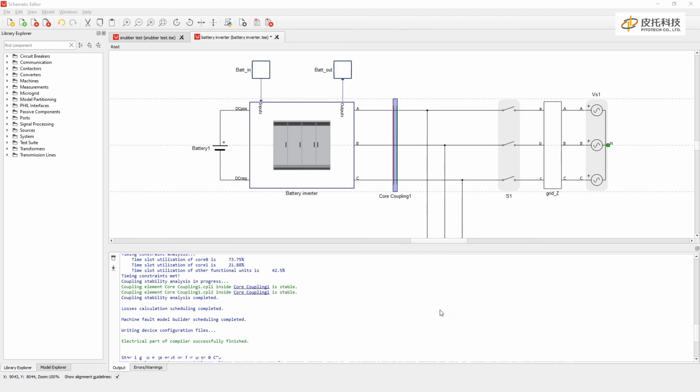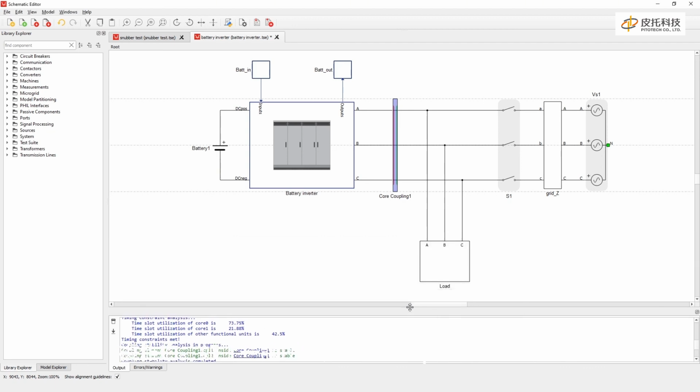Snubber parametrization sometimes can be complicated, especially when models are complex. As explained in the previous lesson, one advantage of TLM couplings is that there is no need for snubbers and thus they are much easier to use. But there are situations when IT couplings are more suitable than TLM. IT couplings are recommended in power electronics applications while TLM couplings should be used in microgrid and power systems applications.